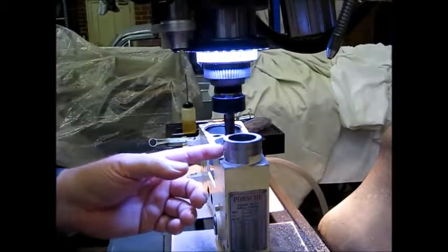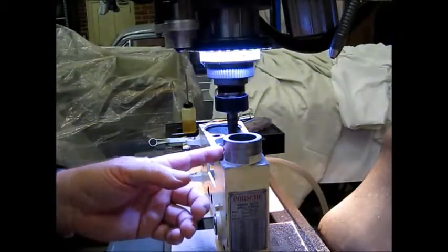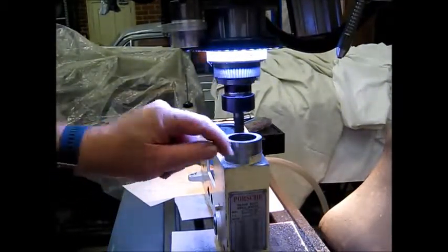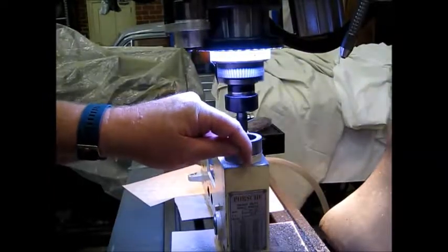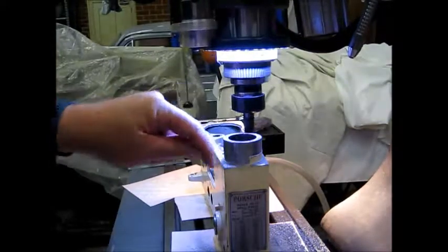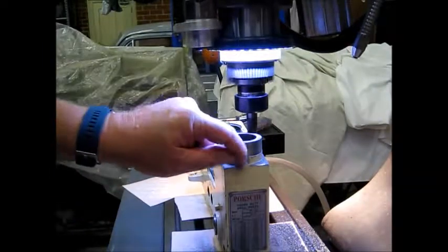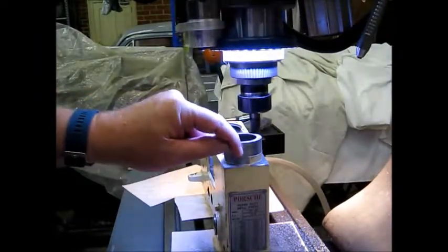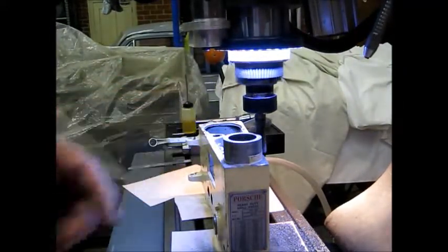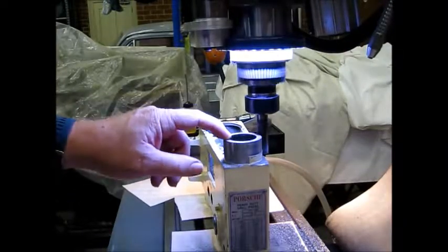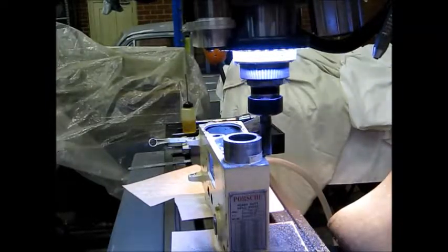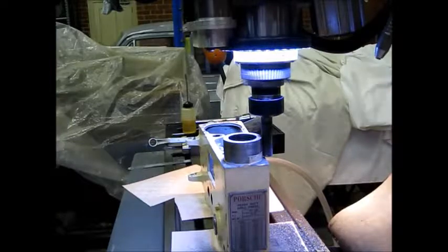I'm guessing there's about a millimetre clearance around this side. So I'm going to try, we're going to plunge in sideways around a millimetre more here and cut at full 30 millimetre cutting length here and do a complete circle. So our next instruction is going to reduce the radius by 1 millimetre, and I'll start that process now so that it seems fairly seamlessly.